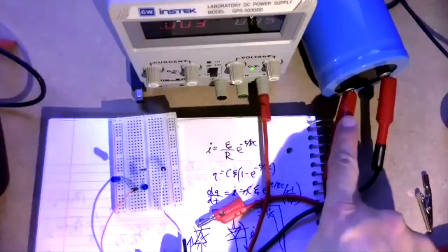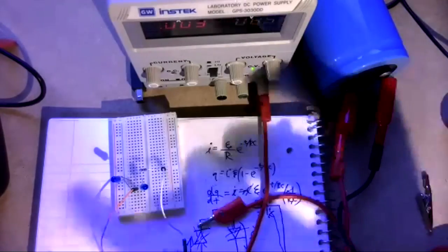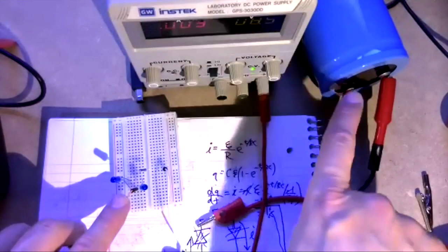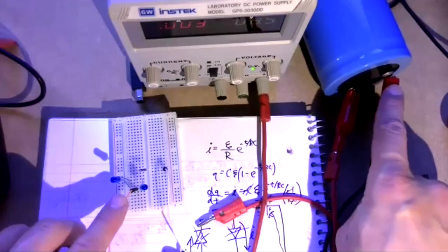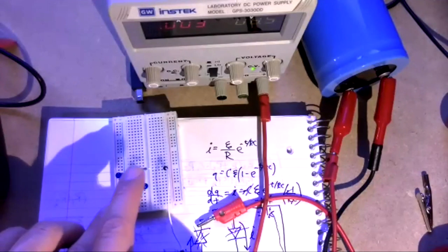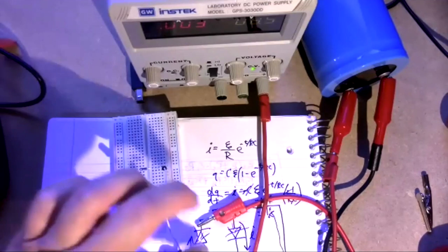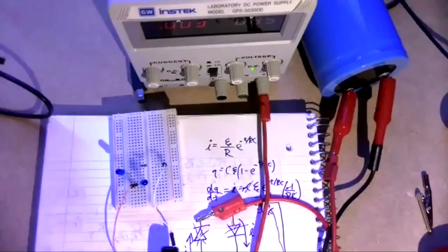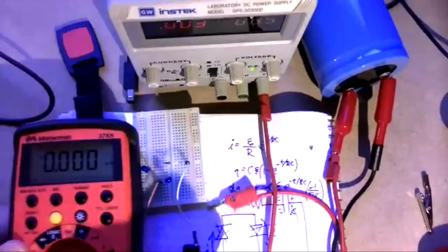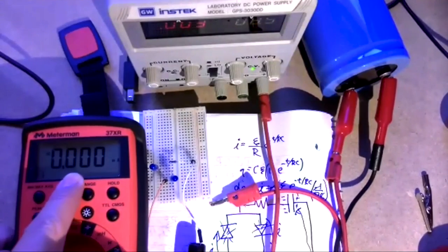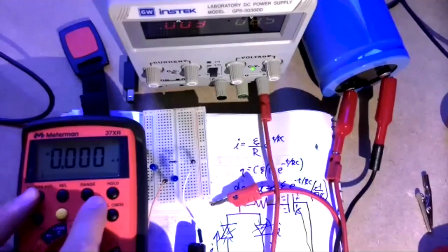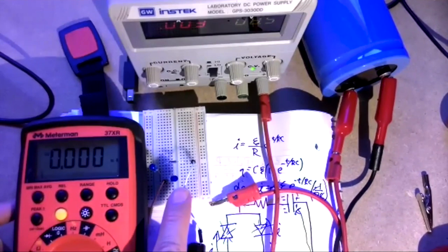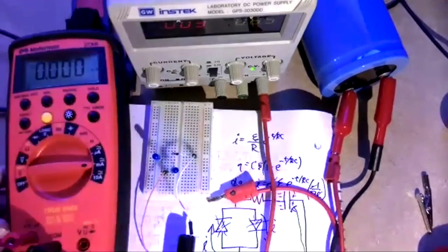So we got this connected over here to our capacitor. The other side of the capacitor, my cables are really long, right? I'm gonna plug in over here. So we're going from our power supply to the capacitor, from the capacitor over to here. Then it's gonna go into this resistor. It'll go through the resistor, and then one other important element I have here, a current meter. We can see the current here, what it's going to be. Remember, if you want to make a current measurement, and we definitely do, we're going to go from over here into our current meter right there.